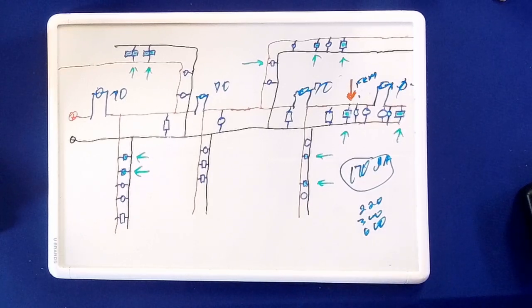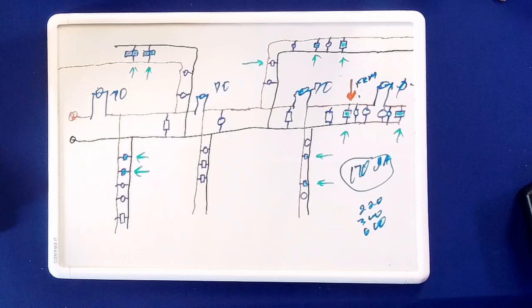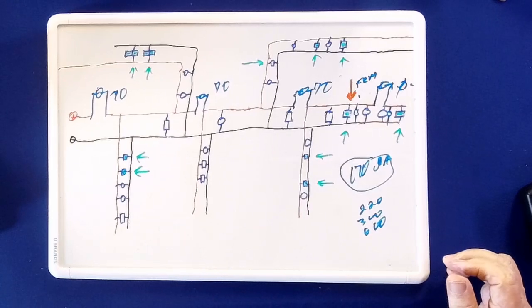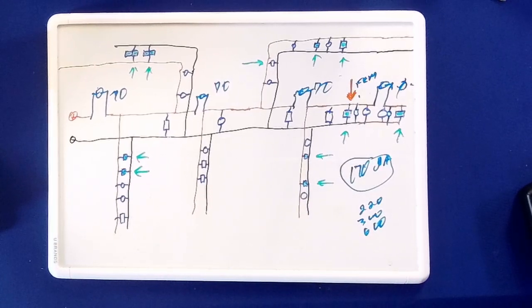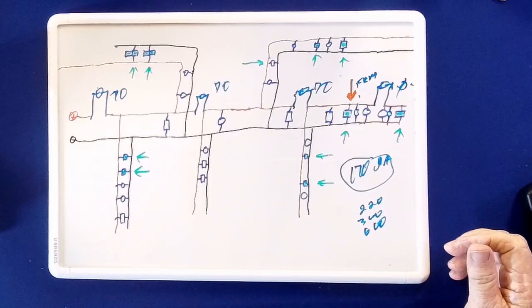I mean, if you see this thing starting to ramp up from 20 mils or 25 mils, because now you're not within a bandwidth, you have a solid battery supply. So you're looking at a fairly stable current draw. You are going to see it move about a bit, but for the most part, it's going to be relatively stable. So if you see this thing going up 1, 2, 3, 5 mils, that in itself is telling you that you have a problem.